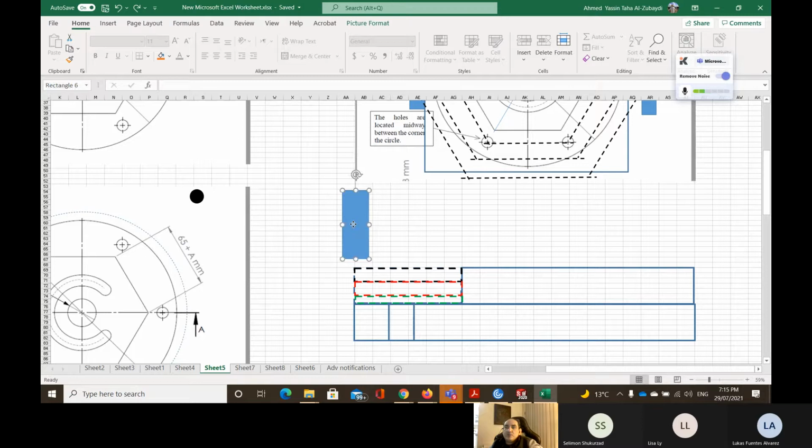Just remember that when we remove material in any operation, we cannot set the cutting tool to the maximum depth and start to remove the material, because this will take a lot of energy. So we always start by steps: layer 1, layer 2, and layer 3. We have something called the rough cut, and finally the finish cut, which is going to give you a good surface finish. This will be a maximum of about 1 to 2 millimeters, depending on the material.